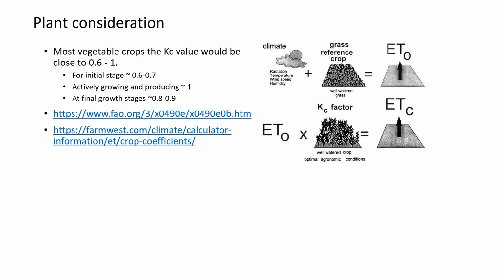This is the reference evapotranspiration that the weather stations pull up, but our plant might need different watering than the amount of reference evapotranspiration, which is usually given by the crop factor. There are a lot of crops, and I can't include all the KC values for different crops at different stages here, so I have the links. These have KC values for a lot of crops.